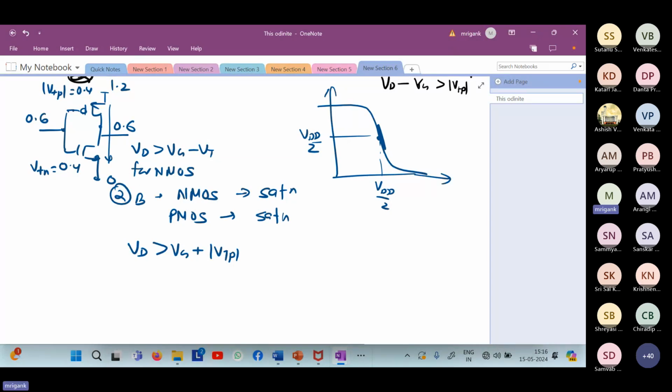So I will get to that biasing point. How do we bias it for amplifier operation? I will revisit that. So just note this point that at this point, both PMOS and NMOS are on and in saturation. The small signal model for saturation region operation is valid, and you can use the inverter as an amplifier in this configuration with this kind of DC condition. I will get back to the actual operation, how you make it operate as an amplifier. But going further in the region 2C, when you get close to this point VDD minus mod VTP.